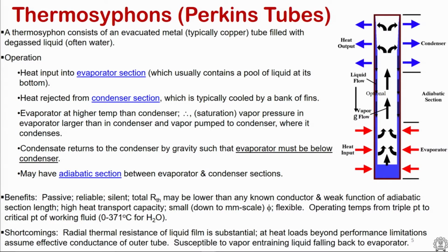the bottom where the evaporator is. And the section between the condenser and the evaporator is often referred to as the adiabatic section. The adiabatic section literally is sometimes misleading. What it means to say is that there is no active process for either dumping heat into the heat pipe or removing heat out of the heat pipe. It is an empty section, but there is no adiabatic condition as such in that region. There could be loss, but it is often referred to as the adiabatic section.